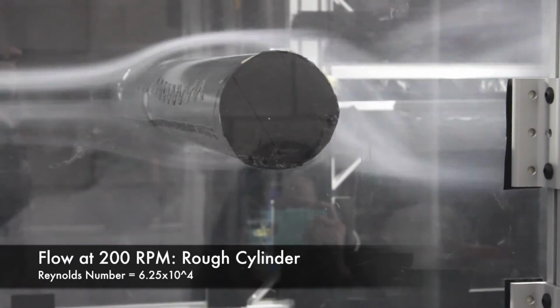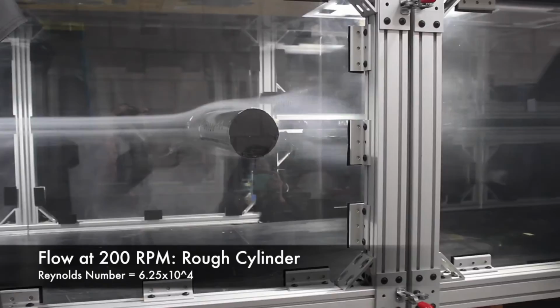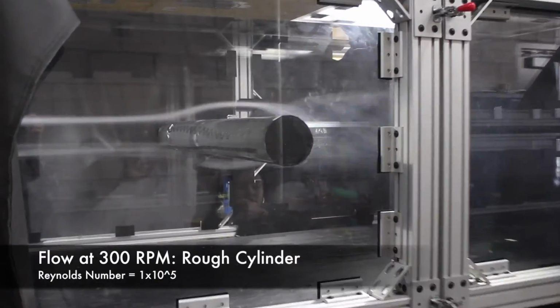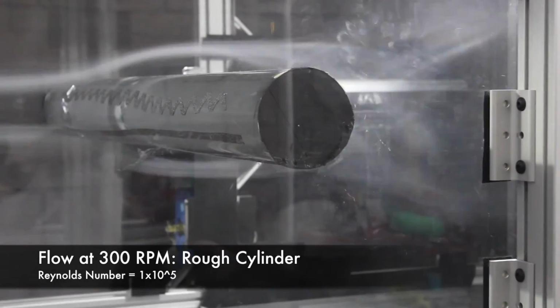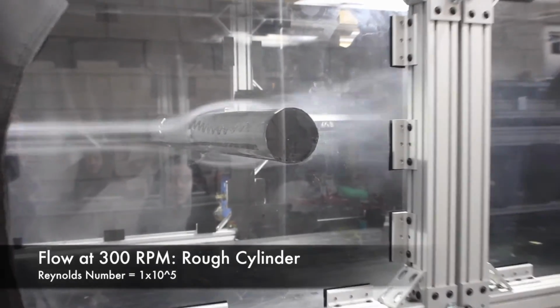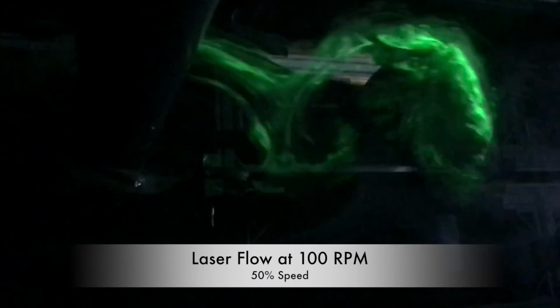The other trip strip, approximately 1 centimeter thick and straight, was placed 45 degrees below the horizontal on the front face of the cylinder. The trip strips were cut from 80 grit grip tape, and the placement of the strips was visually estimated. Once the grip tape was placed, the test section doors were closed and the wind tunnel was started up again.